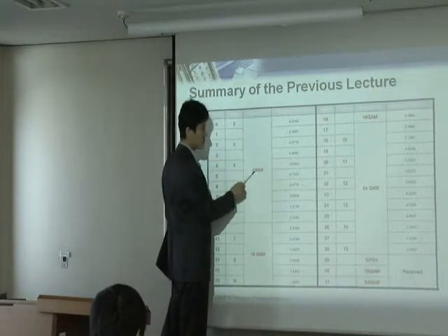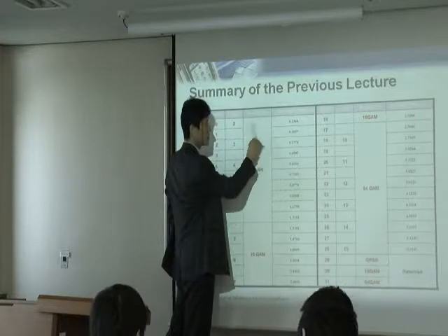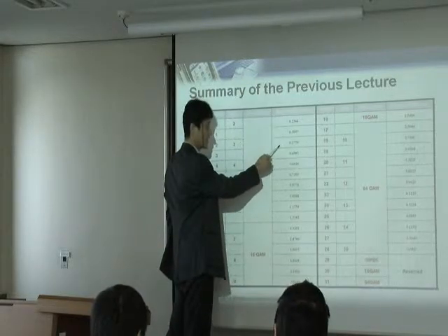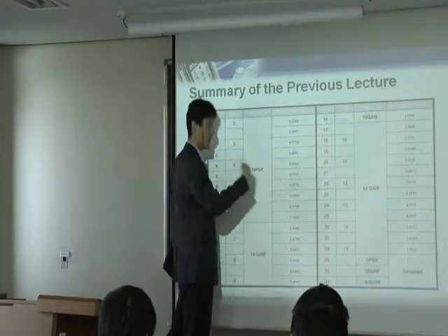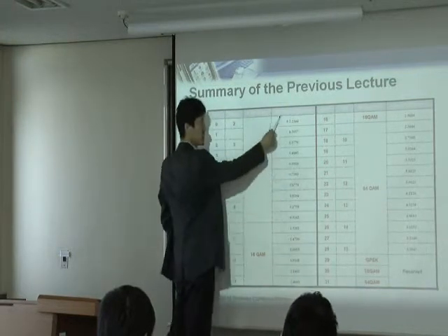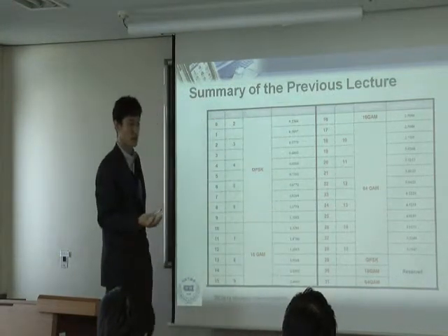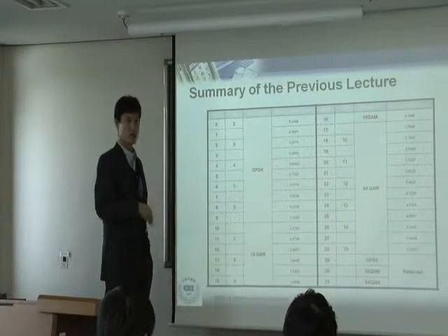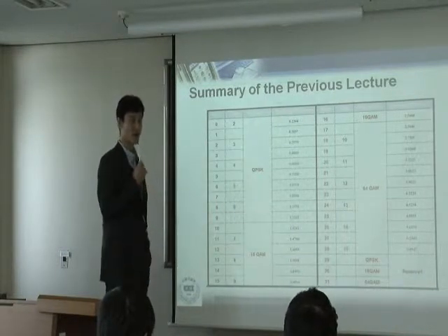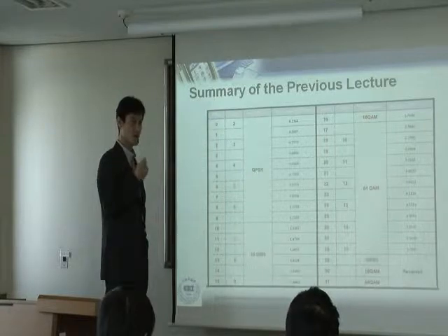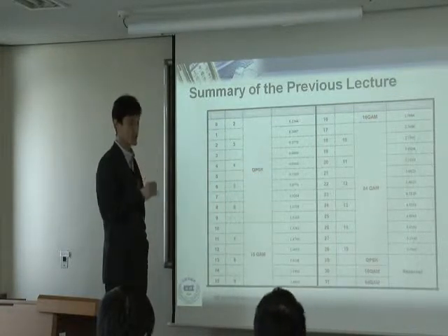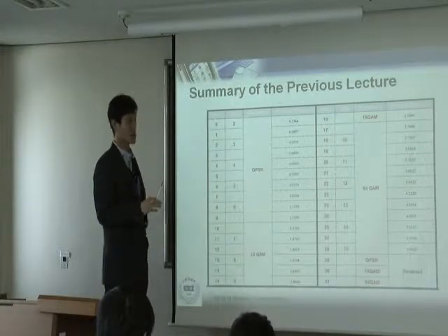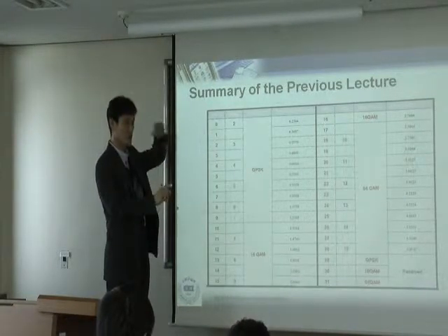Using the same modulation, they change the code rate. They make it higher, higher, higher. Once you raise your coding rate, you get more spectral efficiency. We talked about that, right? So what is the highest value of code rate? 1. Yes, which means no coding, because there is no redundancy. 1 means no redundancy: your input is the same as the output.